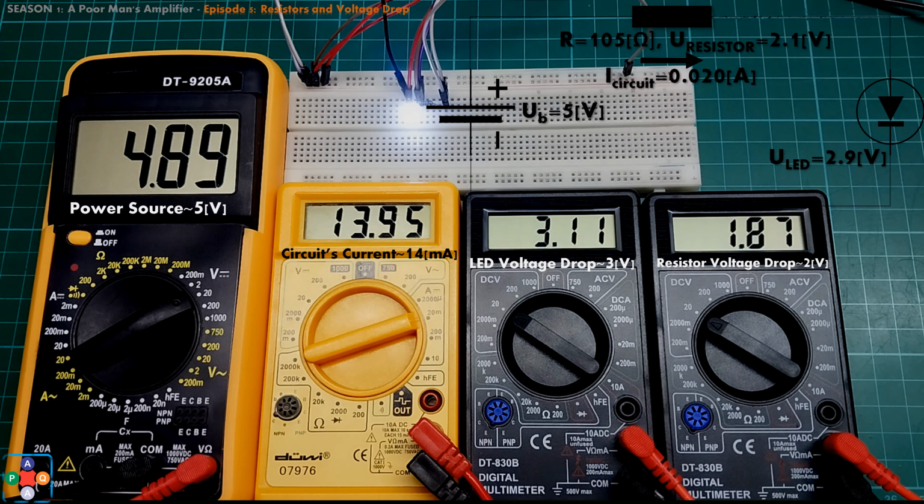Consider scenario where you disregard this rule of thumb, and you go with resistor of lower value than required. Let's say, that by some bad misfortune, there is a sudden increase of voltage in power source. As a result, there is an immediate increase in current flowing through the circuit. Since you have opted for a lower than required resistor, now there is substantial increase in amount of current going through the circuit, and as a result, our LED diode is generating more and more heat, in attempt to dissipate excessive current it is receiving.